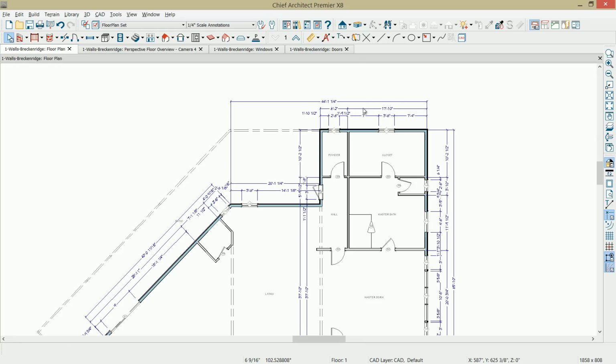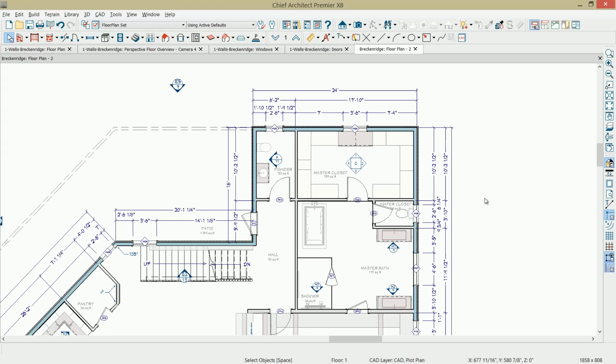Once you clean up the dimensions, a lot of times I'll put those on different layers. In my case, I might take this exterior outer dimension, select it, put it on my exterior layer, my walls layer, and then my openings layer. That way I can make a very clean floor plan look.